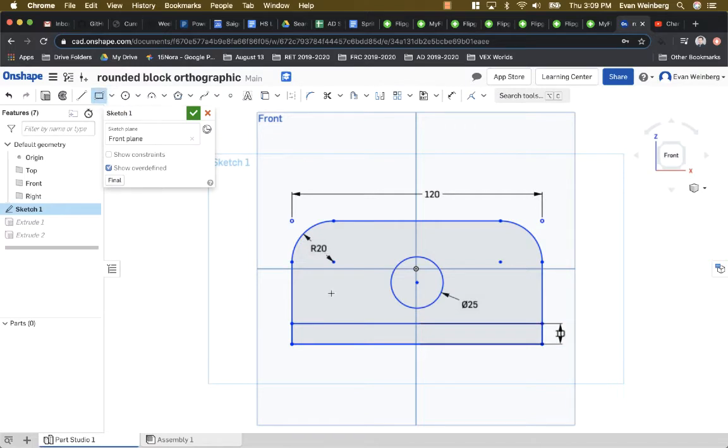So I'll show you just one more example. Let's say I wanted to make a square where it was 8 millimeters to the side. All right, so the first thing I might do is go here, and it was pretty close, so I'll make that 8 millimeters. And I could make this also 8 millimeters. But the other thing to know is maybe I want to very accurately place it so that it's how about 10 millimeters away from this surface right here.